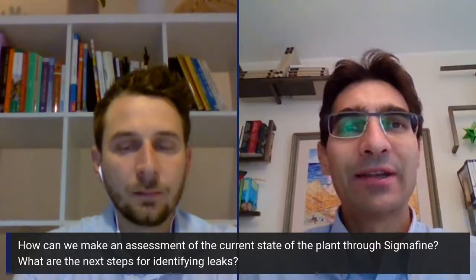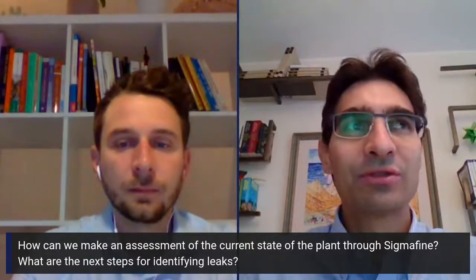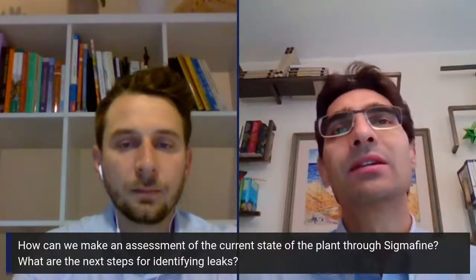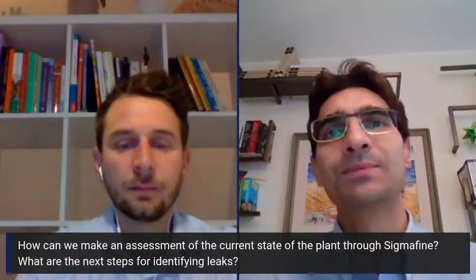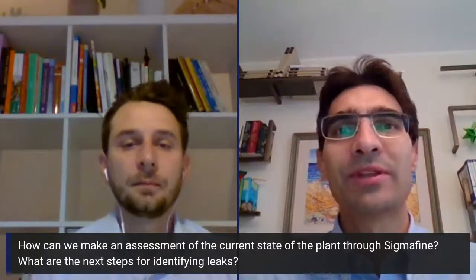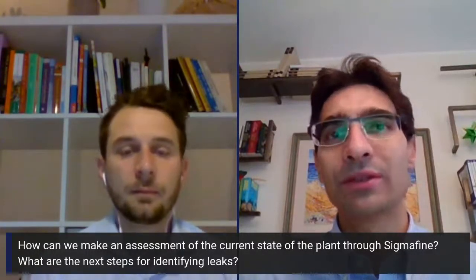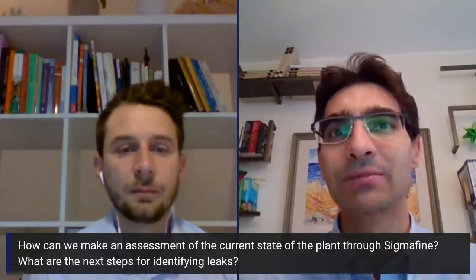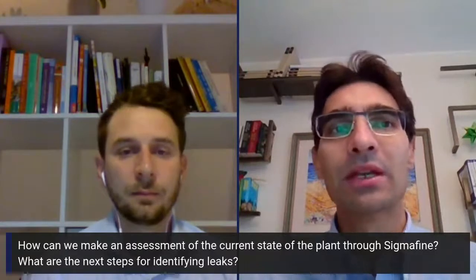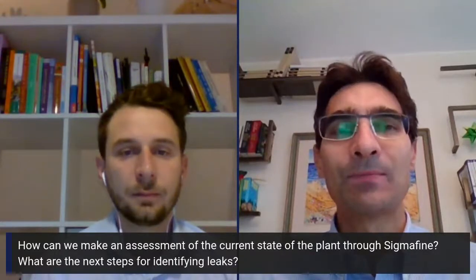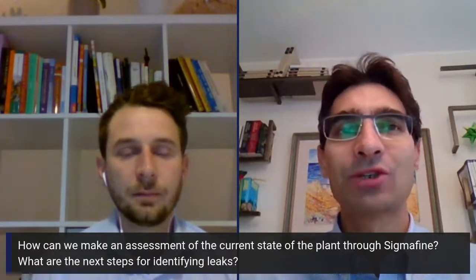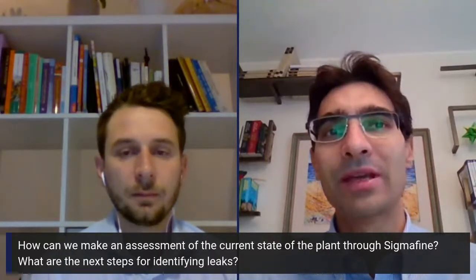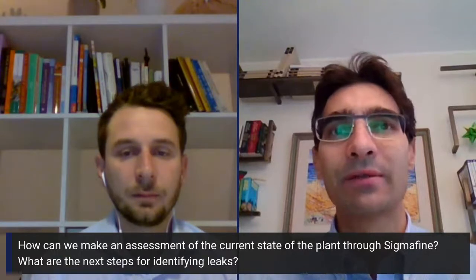And regarding leak identification, leaks typically are much lower streams compared to the usual flow rates or inventory changes that you typically deal with. So again, looking at this information on a monthly rather than a daily basis allows you to make a leak more evident.